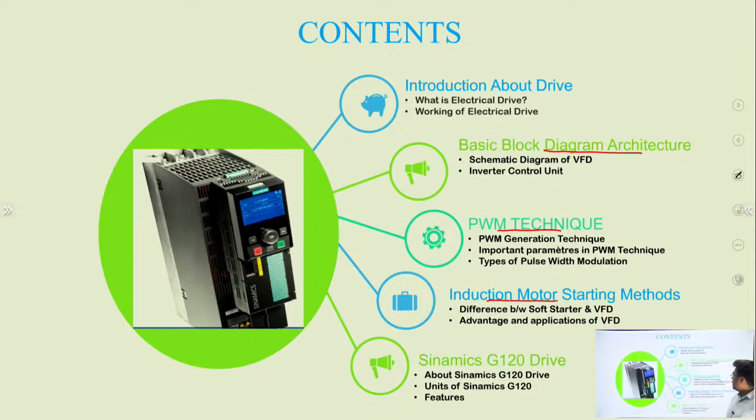Basically I have covered the VFD device, which is used for induction motor starting. So I will give you a small introduction to the different types of induction motor starting methods, and which ones industry uses. Basically they use a soft starter and the VFD device.